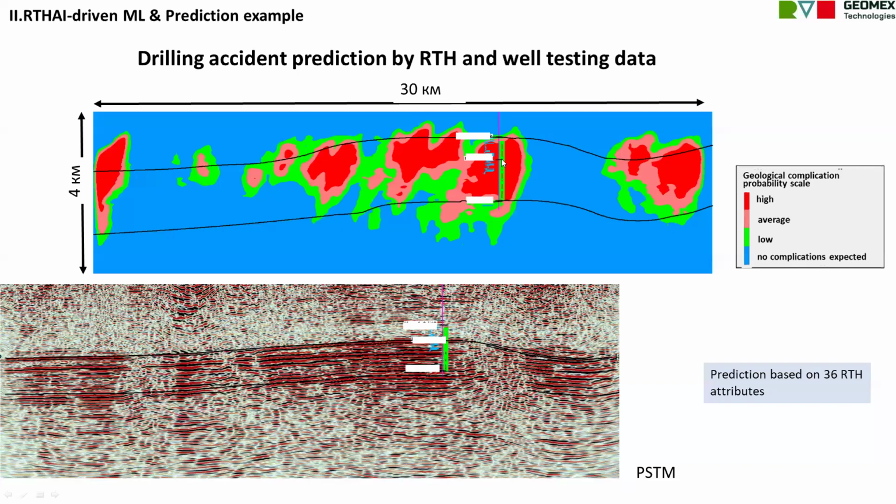It can be 100%, normally described as a percentage. Besides shallow gas accidents or blow-ups, we normally are very careful about lost circulation, because it aggravates the cost of drilling, as well as causing downtime. We normally associate fractures with lost circulation. So when we're talking about drilling accidents, do you mean drilling lost circulation? That is my question, sir.